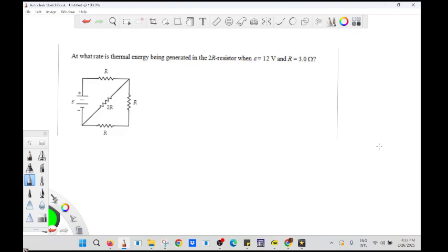Okay, almost done. So this one is just the schematic that can be confusing. So what you can do, you start from here. So I'm going to do this schematic here. You start with the EMF, which is 12 volt. You have a load here. So I'm going to put a load here. And then you have two paths. So it means we're going to have two branches. And this is one branch, even though it makes like a corner, it's just one branch, because there is no intersection.